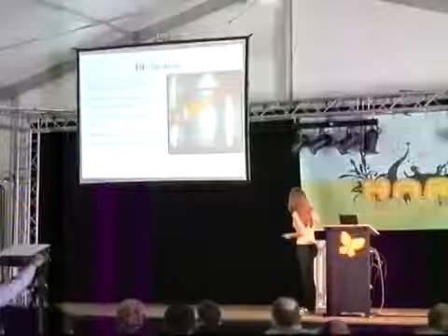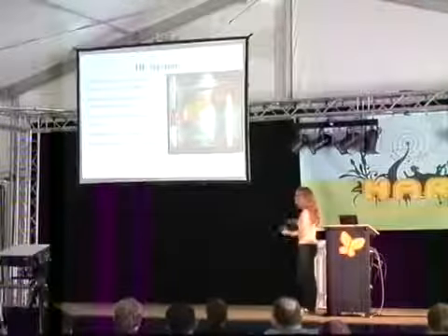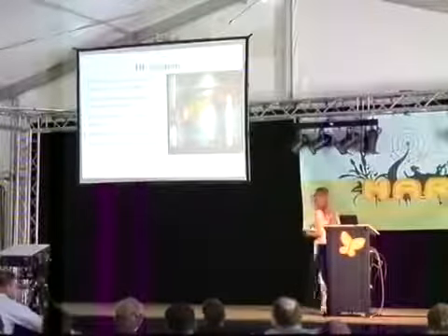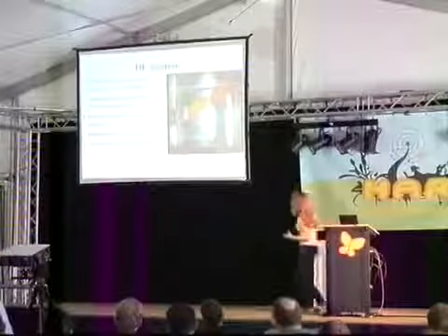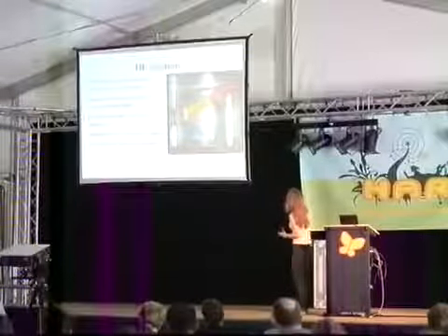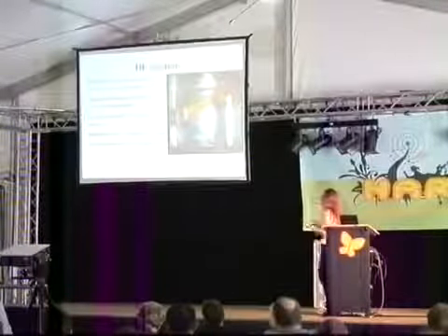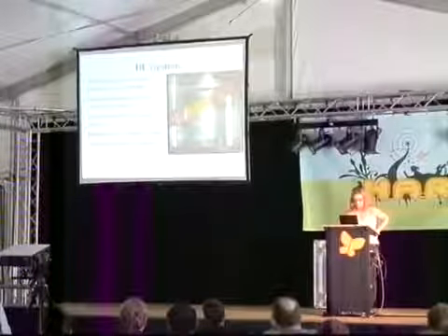So here are just the BNC connectors to your function generator here and up here. If you just make little standoffs out of Delrin, it keeps the system from arcing. Those, just as an aside, are the gauges of wire I used, but obviously you can change depending on what you want it to be.